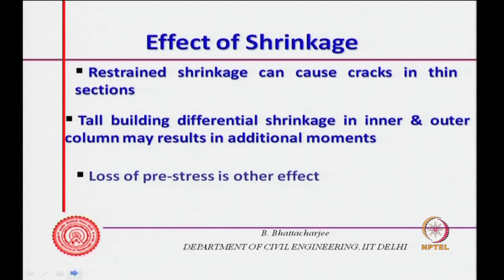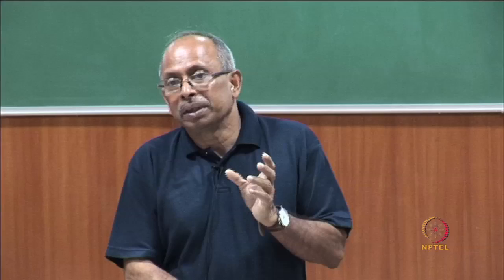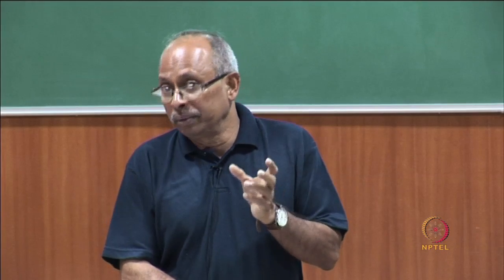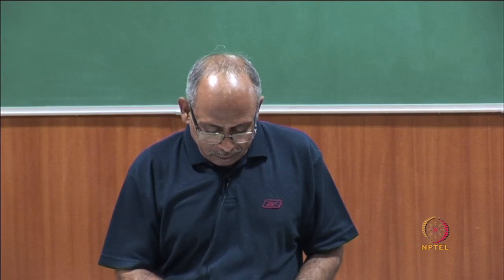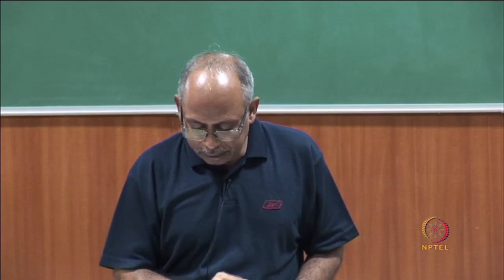Loss of pre-stress is of course the other effect, because shrinkage means the natural dimension of the concrete would become smaller. If it is restrained, this would cause loss of some pre-stress, because the concrete would have tried to come to this smaller dimension because of shrinkage, but you have restrained it. In other words, you are actually applying a kind of tension. So the pre-stress loss can be there because of the shrinkage of the concrete itself. So, this is another effect.